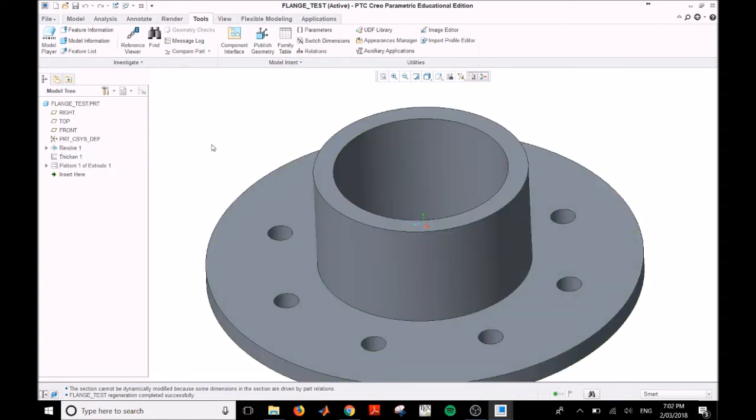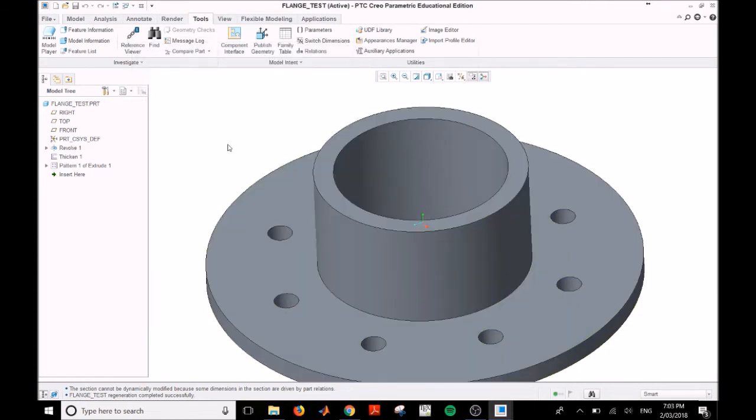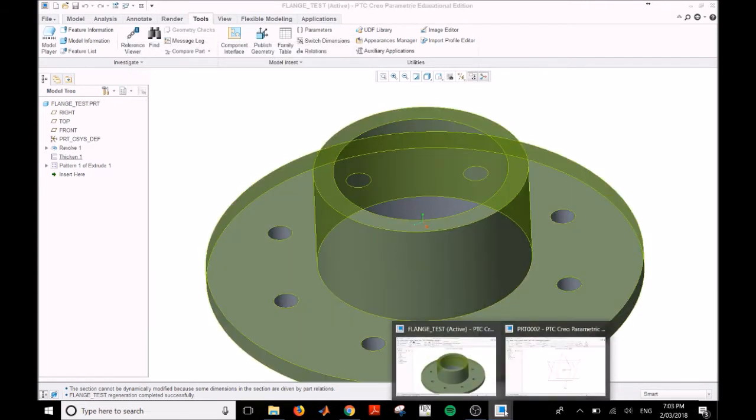Once you've done that, you can then name dimensions. Creo uses a pretty crude and difficult naming convention. It's much more meaningful as a user to name them yourself. And once you've named them, in the Relations tabs you can then enter your relationships. So we'll see how that works with a new model.